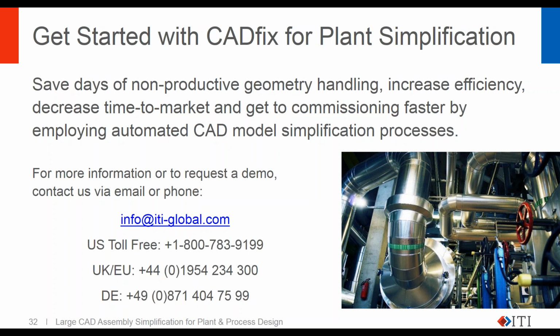So CADFix can read native CAD models from CATIA, NX, SolidWorks, Inventor, AutoCAD, and Creo, and we can also read a lot of the collaboration formats, so STEP, IGES, SAT, JT, STL as well, although we don't see a lot of STL. So yeah, all of the major CAD formats and neutral.